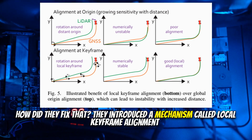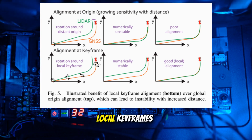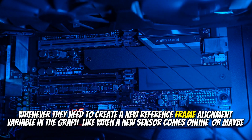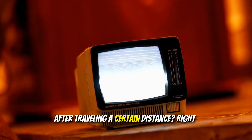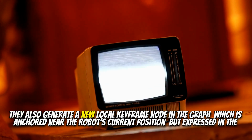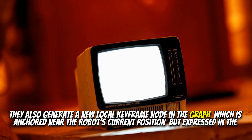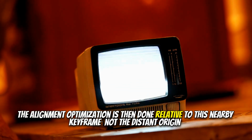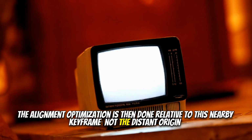They introduced a mechanism called local keyframe alignment. Local keyframes. How does that help? Instead of always relating the local sensor frame directly back to this single, potentially distant global world origin, they do something clever. Whenever they need to create a new reference frame alignment variable in the graph, like when a new sensor comes online, or maybe after traveling a certain distance? Right. They also generate a new local keyframe node in the graph, which is anchored near the robot's current position, but expressed in the world frame. The alignment optimization is then done relative to this nearby keyframe, not the distant origin.